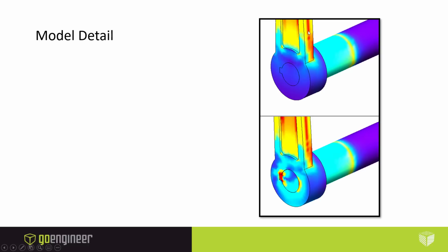But now notice, it still didn't make a difference up here. Same stresses up here. It's really just locally that it made the difference. So if you know the keyway is fine and it'll last, it's not going to have any issues, then okay, just bond them together there and move on. Get results where you care about them.